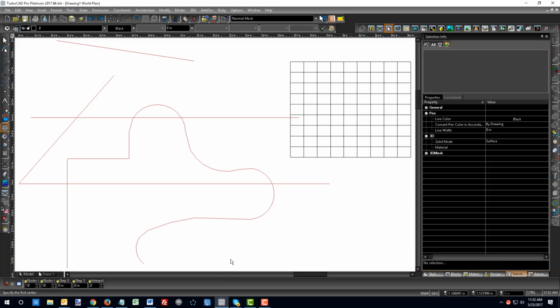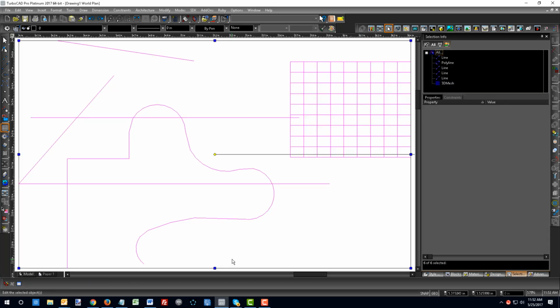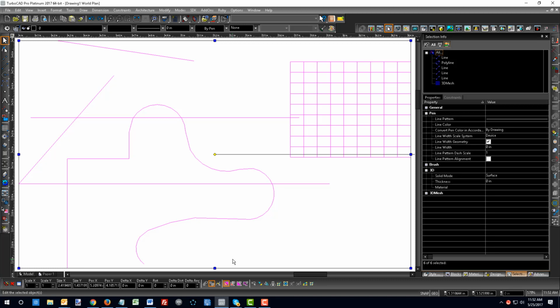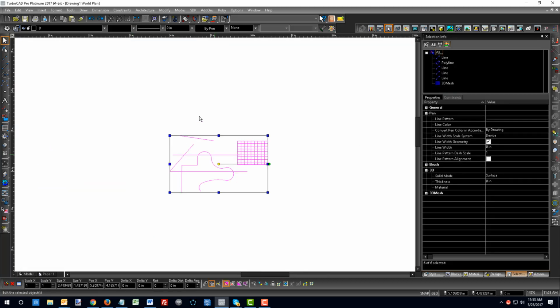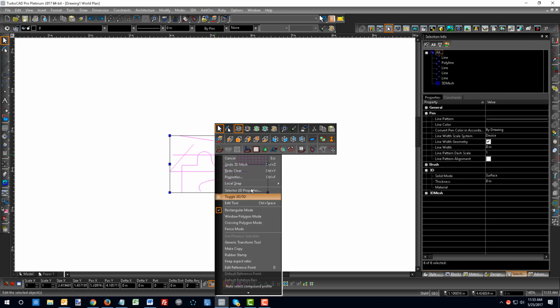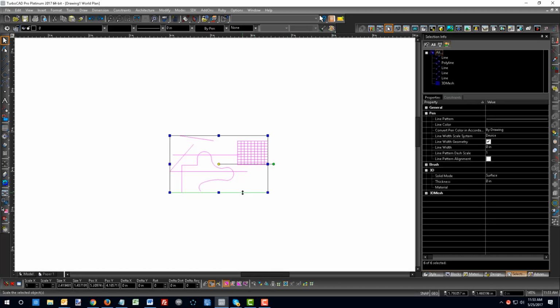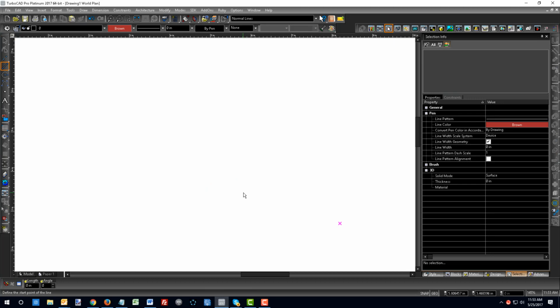Okay, so now let's go back to TurboCAD and talk about some of the 2D drawing basics. I'm going to use Control A to select all, and I'm going to hit the delete key to clear my desktop. That's actually a pretty common question: why is there no erase option in TurboCAD? You'll notice there's just simply not an erase or delete key functionality listed. However, anytime you select objects and just hit the delete key on the keyboard, you are effectively erasing those objects.